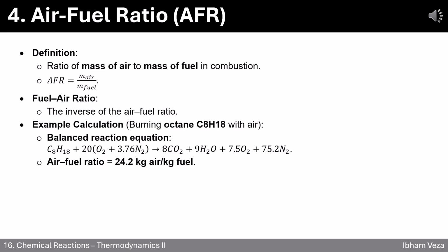4. Air-fuel ratio, or AFR. Next, let's break down the air-fuel ratio, or AFR. This is simply the ratio of the mass of air to the mass of fuel during combustion. It tells us how much air we need to completely burn a certain amount of fuel. There's also the fuel-air ratio, which is just the opposite, fuel over air. To make this clearer, let's look at a simple example.